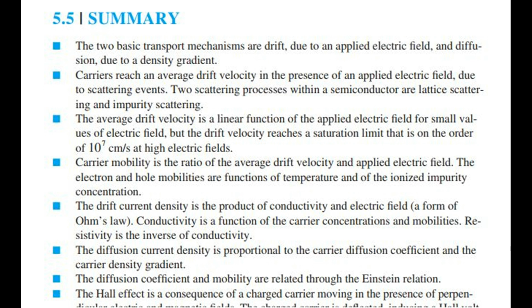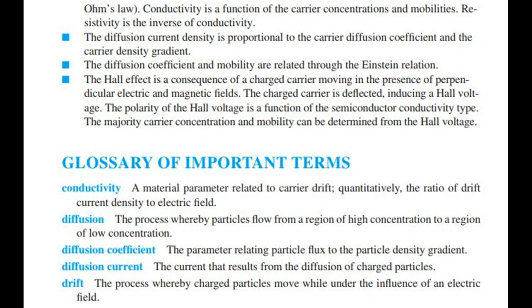The Hall effect is a consequence of a charged carrier moving in the presence of perpendicular electric and magnetic fields. The charged carrier is deflected, inducing a Hall voltage. The polarity of the Hall voltage is a function of the semiconductor conductivity type. The majority carrier concentration and mobility can be determined from the Hall voltage.